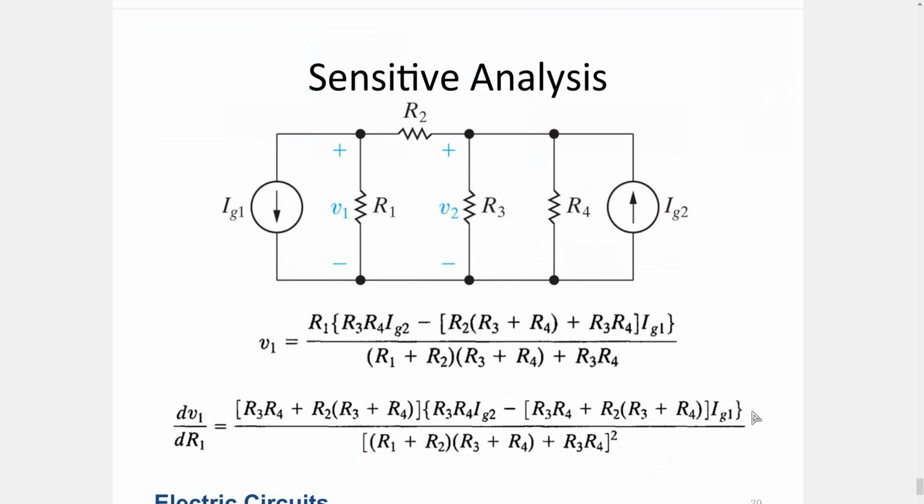Now, there's another thing called the sensitivity analysis. Actually, we have learned how to do it with the help of LTspice, but from a theory point of view, what we have done there, or how it's achieved, is this: sometimes we are interested in certain node voltages or mesh currents, whatever, some circuit variable, and you want to explore the dependence of that circuit node voltage on a particular variable. Typically, it's a component value. What happens if the component value shifts to my variable? This is called the sensitivity analysis.